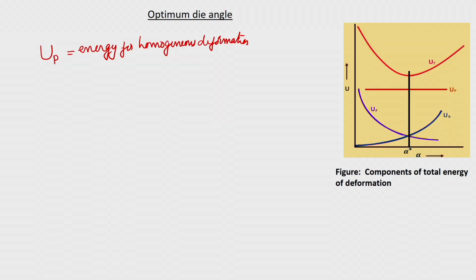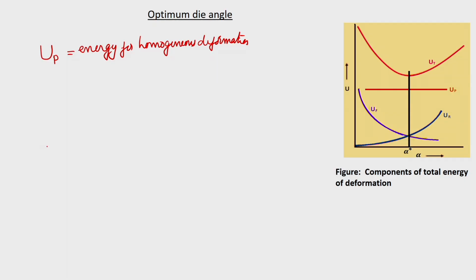Now, if you just look at it with a die angle, let us say a conical die angle is coming. With the die angle decreasing, two things are happening. For example, I am just getting from say maybe diameter of this to a diameter of this. So, this is the reduction which is taking place, and this is going to be my die angle. Okay. So, this is your 2 alpha. This is the 2 alpha angle.